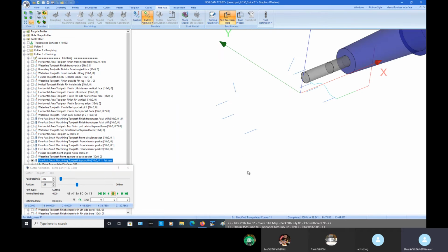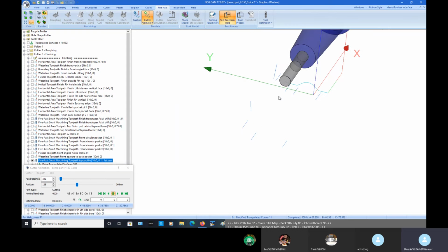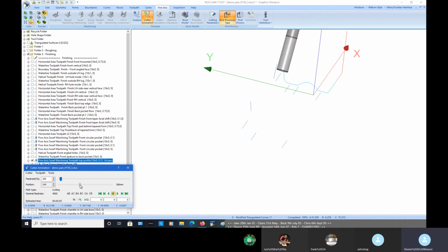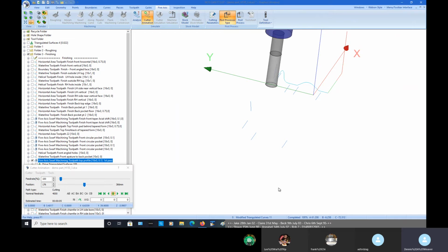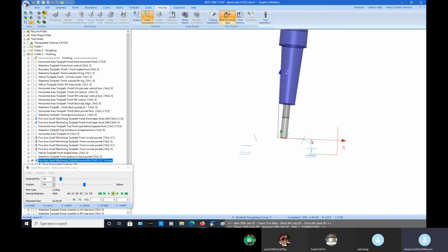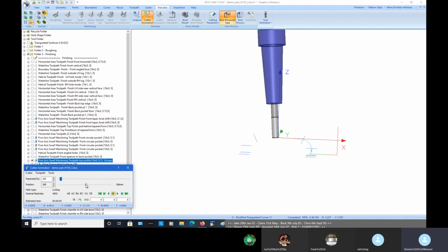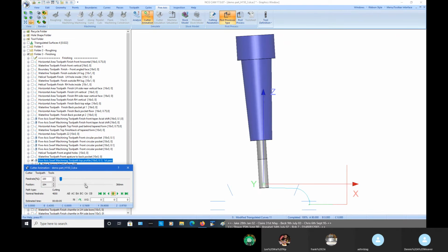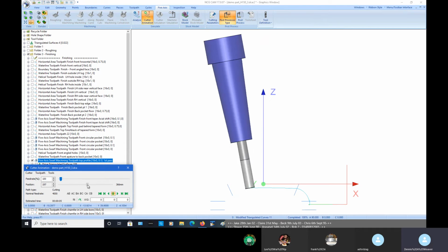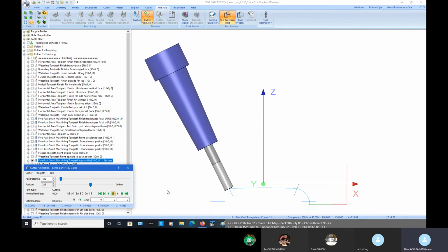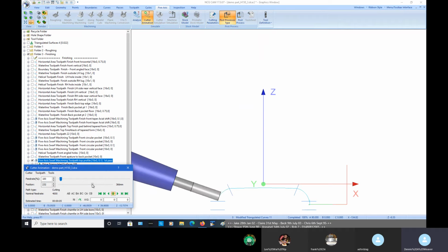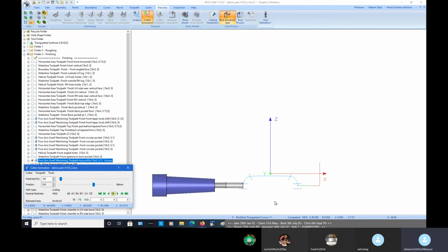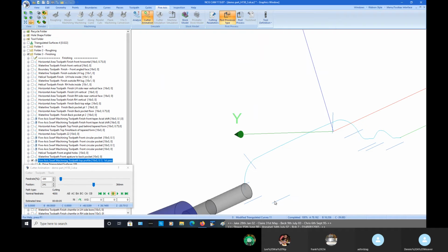okay, so we're still in line at this point, and then we start to crank the tool up and over as we roll around this top edge. As you come over the center line, you should be almost vertical. See if I can get that centralized. And then you pick up the angle for the next curve that's given the direction for the tool axis. And then as we come around the far side, we're back in line again.